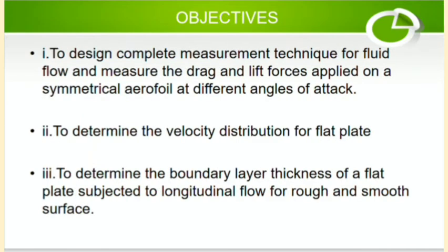For the objectives, we have to design a complete measurement technique for fluid flow and measure the drag and lift forces applied on a symmetrical aerofoil at different angles of attack. Second, to determine the velocity distribution for a flat plate. And third, to determine the boundary layer thickness of a flat plate subjected to longitudinal flow for rough and smooth surfaces.